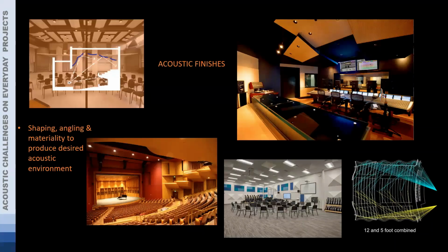One of the ways that we get involved in the design is the acoustic finishes. There are many spaces that require very careful shaping and angling and very specific materials, such as the spaces that you see here: recording studios, theaters, concert halls, band spaces, music performance. But other typical spaces, classrooms, offices, airports, may not need that kind of very detailed acoustic design of the finishes, but do need to incorporate them so that they aren't essentially a racquetball court.